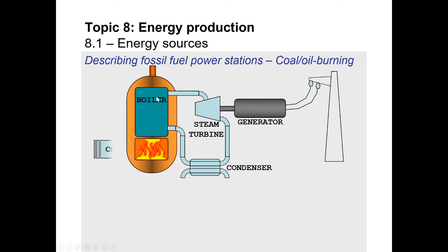So steam is produced, that steam gets pushed through these pipes, right? So the steam goes and turns a generator, well, it turns the turbine, which then turns the generator, which produces your electricity. The steam then comes down these pipes through the condenser, right? There's cold water moving through the bottom, moves through this, becomes liquid water, and gets pumped back into the boiler. So this cycle repeats itself. Now, if we want to look at this from the perspective of a Sankey diagram, you've got the chemical energy from the coal.